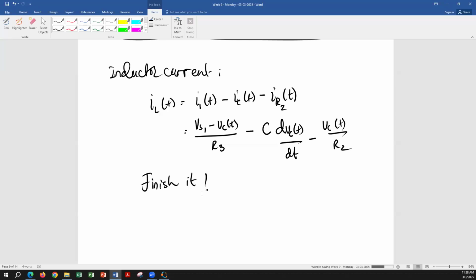A steady state value of sinusoidal response is still going to be sinusoidal because the steady state value matches what type of source you have. If you have a DC source, your steady state value is a DC value. If you have a sinusoidal source, your steady state value is a sinusoidal value. If you have a square wave, your steady state is a square wave. Now, everything will have transients because as long as you have capacitors and inductors, you do have transients. But when we are discussing steady state, we ignore transients and only concentrate on what's going to happen when all the transients have died out and you have a steady state response.